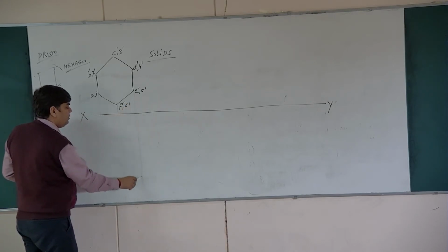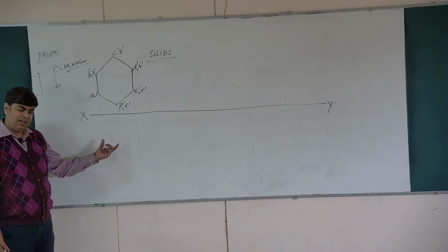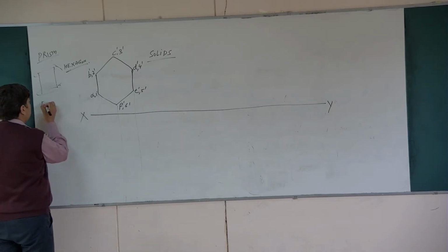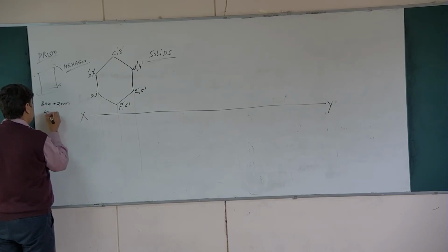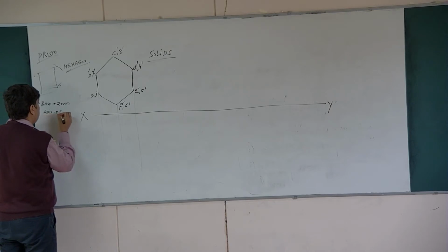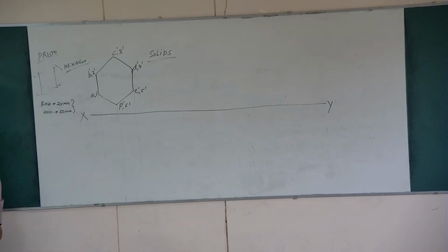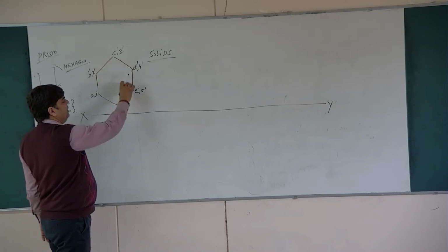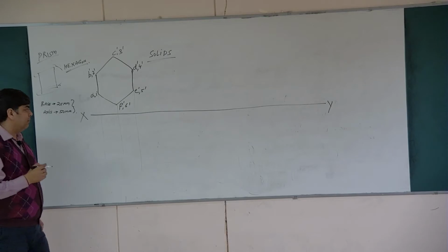You have to use pencils in such a way that projection lines should be as light as possible. Now the edge of base is 25 mm and the axis is 50 mm. This is the basic information about the hexagonal prism, such that AB, BC, CD, DE, EF are all 25 mm. And now we have to locate the axis height.